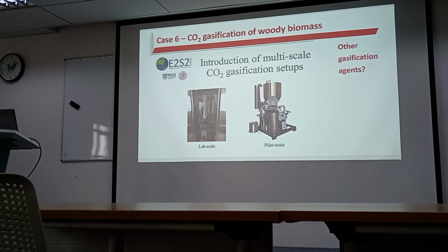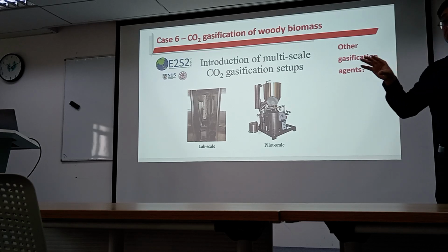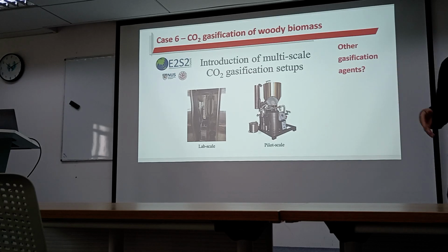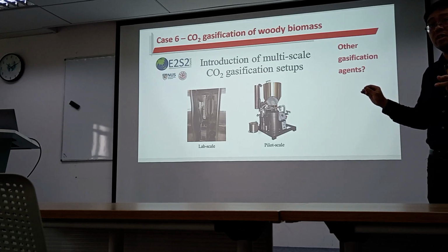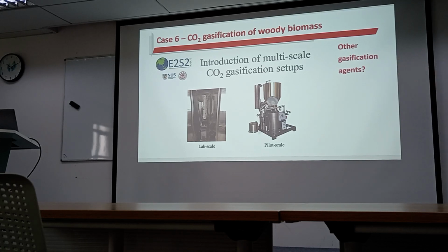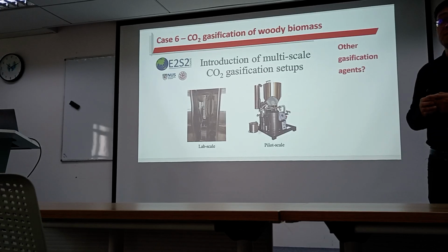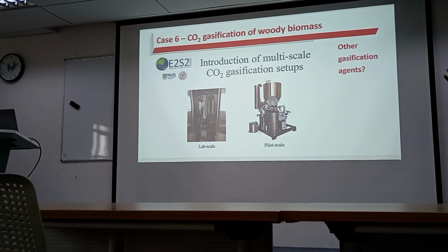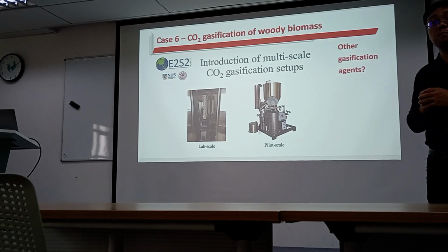Another one is that for the reduction of greenhouse gas emission, it is correct. Because in this process, carbon dioxide is a greenhouse gas, but this researcher uses carbon dioxide as a source to operate the gasification process. In this case, he can convert the carbon dioxide into carbon monoxide and hydrogen. The carbon dioxide is used and creates new gases, carbon monoxide and hydrogen. From this angle, this process also has a function for reducing greenhouse gas emission.